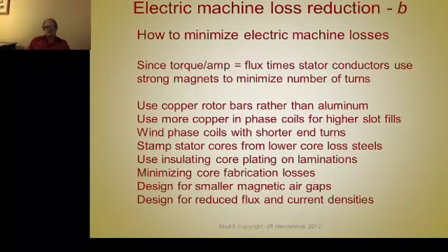So the point is, some companies nowadays, these core loss issues are so serious that they're measuring the core losses of the entire stator. We offer a service to do that, as a matter of fact. So you could try different fabrication methods of stators and measure the whole core loss per pound.